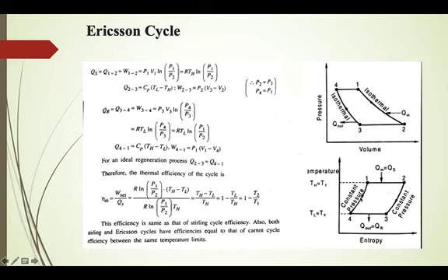It is same as Stirling cycle. The only difference is that the heat transfer happens at constant pressure. Internal heat transfer from the working fluid to the regenerator and from regenerator to the working fluid both happen at constant pressure over here. Okay.